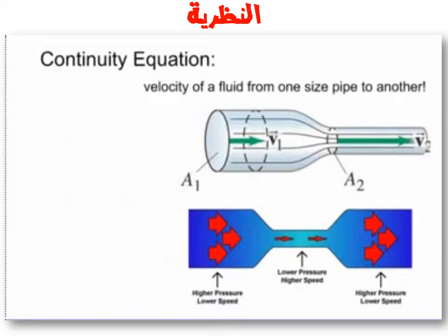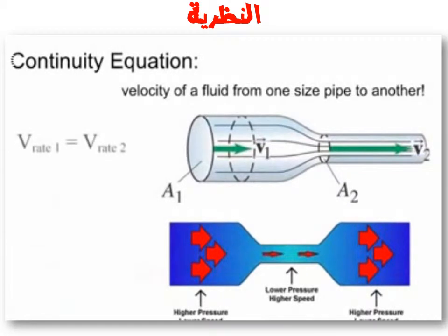It's pretty fun. And so here we can use the volume rate of flow at one point is equal to the volume rate of flow at the other point. It's conserved. Something you'll see is Bernoulli's equation. It's all about conservation here. That means the area times the velocity, A1V1 equals A2V2. Anytime you have pipes changing, use A1V1 equals A2V2.